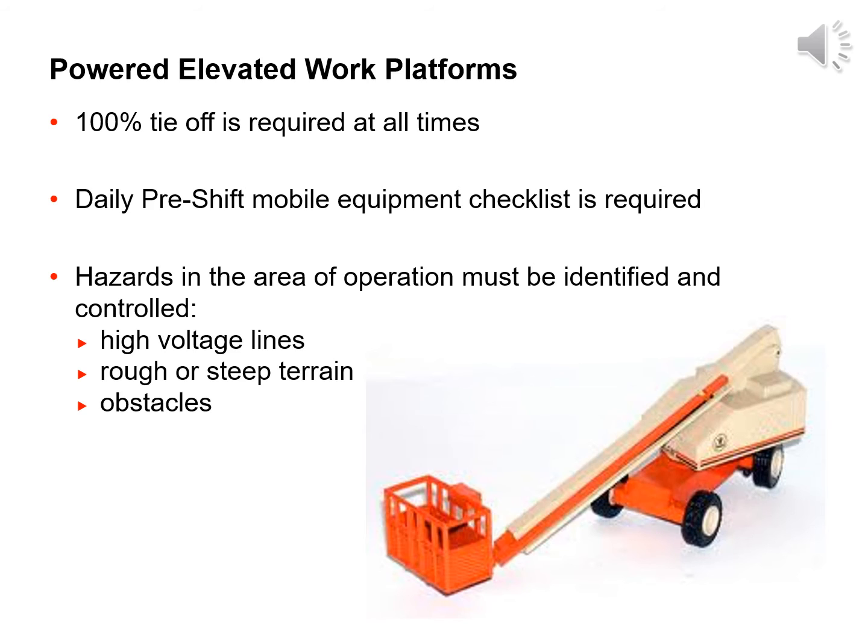You should elevate the platform only when it is on a firm, level surface. Although many lifts look like a rough terrain piece of equipment, they are not. Their large tires do allow the equipment to access somewhat difficult areas, but once in position, they are designed to only be out of level by 5 degrees while in operation.